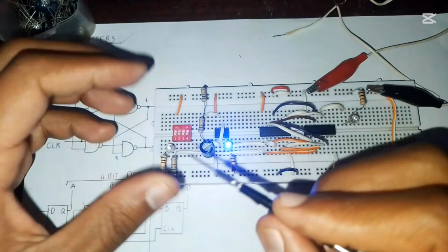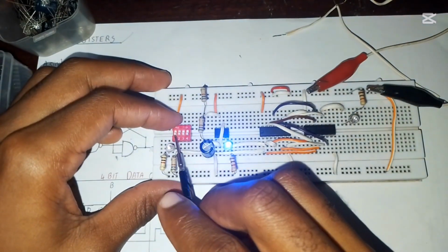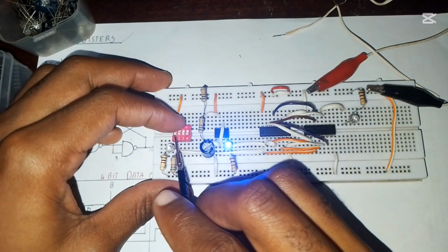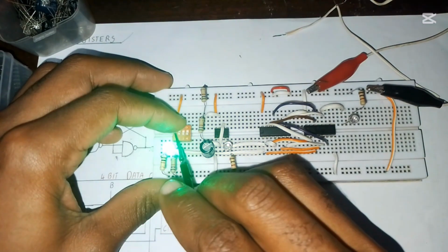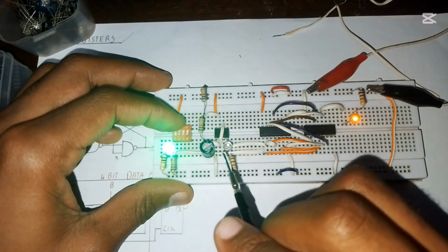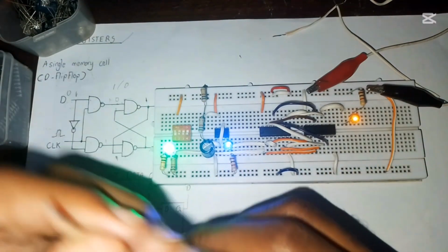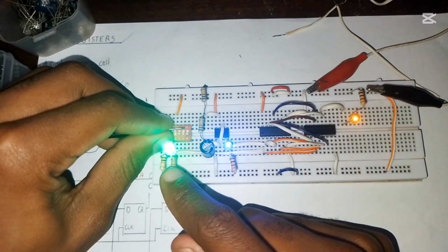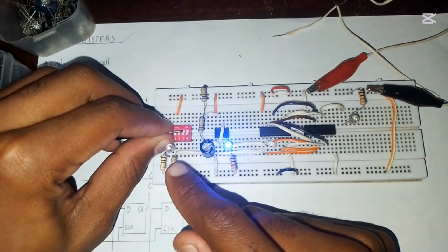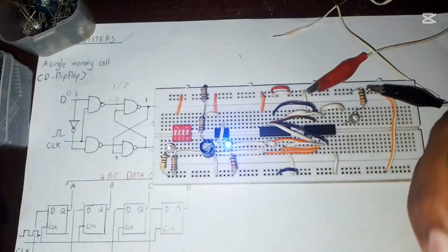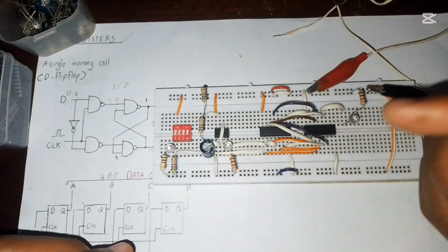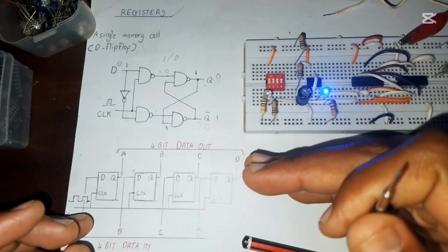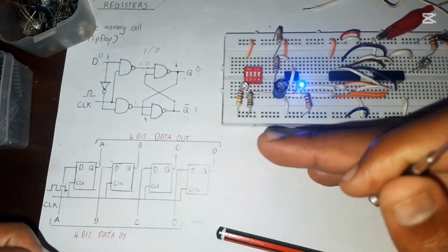So we can do that again. We're going to wait until the clock is low for us to turn this on. So let's see, it waits until the clock is high for it to change the output. Then we are going to turn it off. Now, like that, it waits until the clock is high again to change the output. So basically our circuit is controlled by a clock pulse. The clock pulse is what mostly controls our circuit.